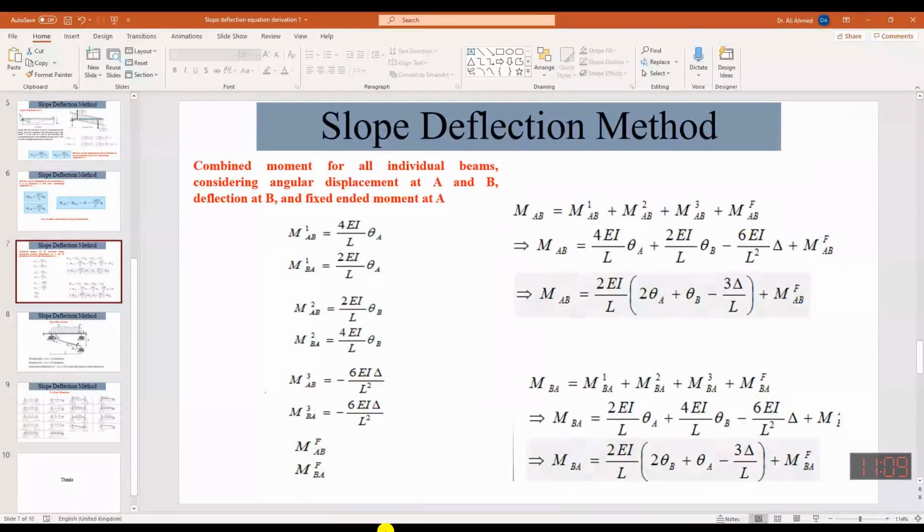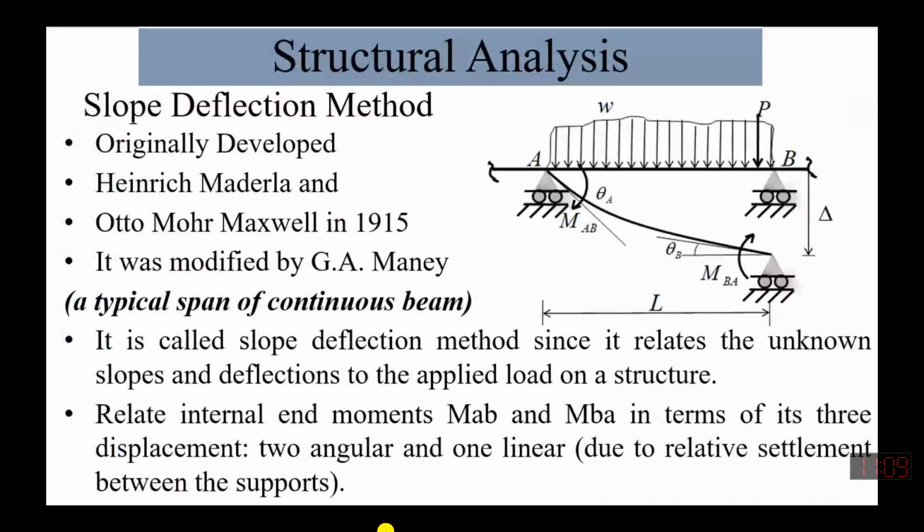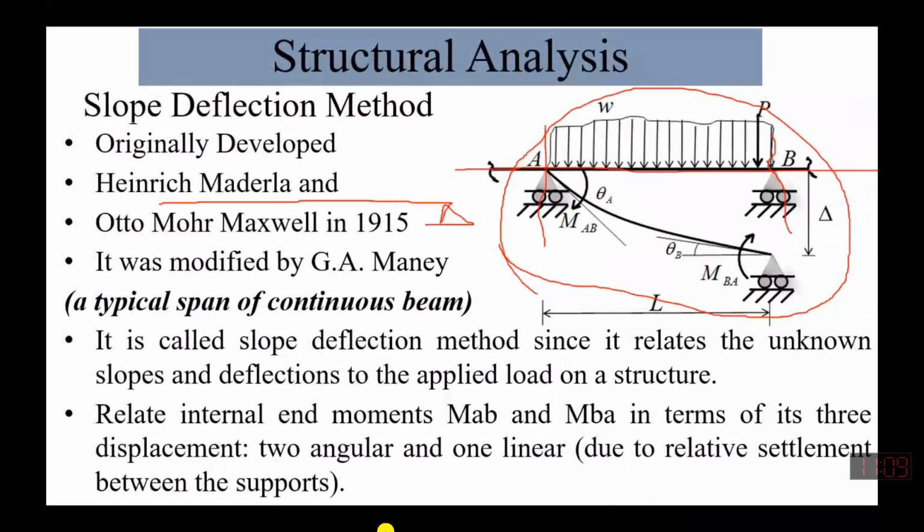Now, after these two relationships and sign convention for moment, we'll go to one more part. In this derivation, we considered a continuous span, an internal continuous span, a typical continuous span within the beam. Let's say this is going on like this. But if your far end is pin or hinge or roller, something like this happens.